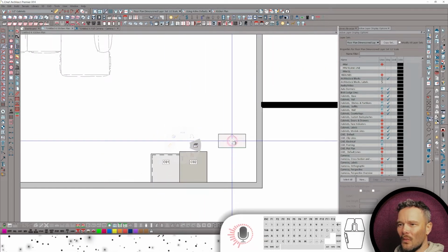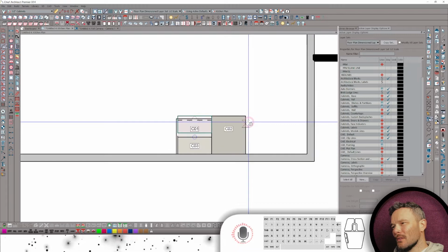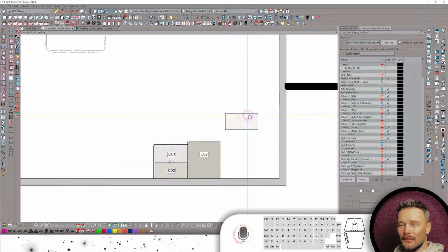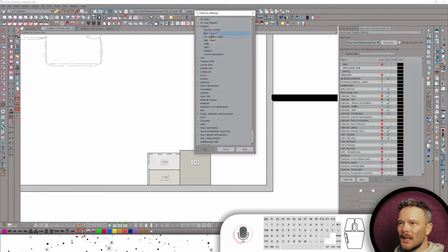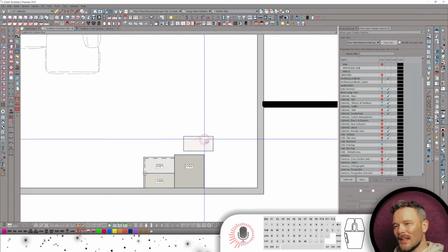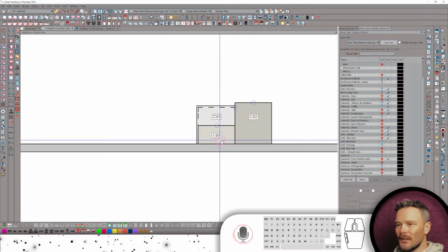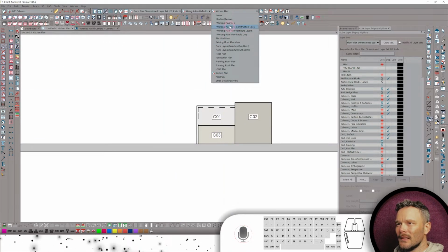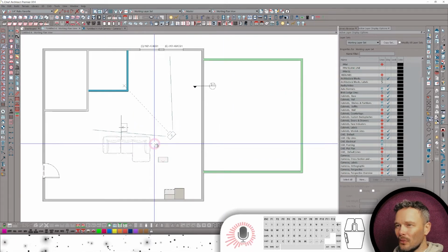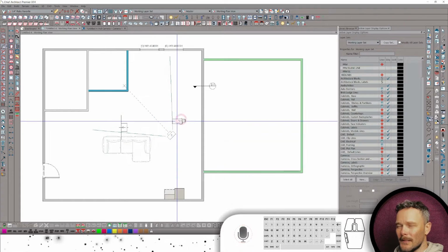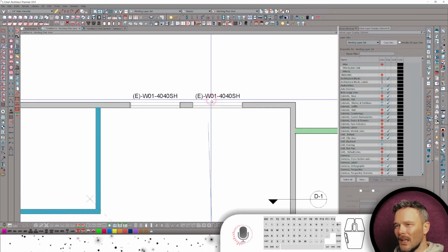And let's actually show a wall as well. Here's a wall cabinet. So kind of a brown schema. You can of course edit these in your defaults underneath cabinets, and here we go. Just looking in here underneath cabinets, you can see base cabinet, full height, and wall cabinet. You can edit these as you need to if you don't like this color scheme, or if you'd like to switch a couple things around. There's a little bit of a transparency in this wall fill, so hopefully take a look at, and you can see there's no labels in the working plan view. I like things to be really, really clean when I'm working and discovering things. Now, something you may see right now is that on the windows, there's a label here and it shows existing.